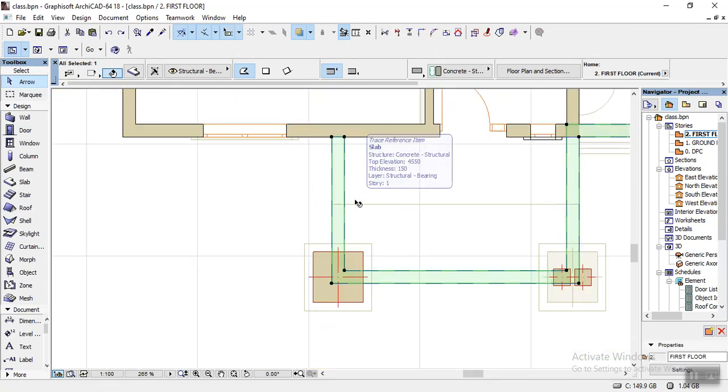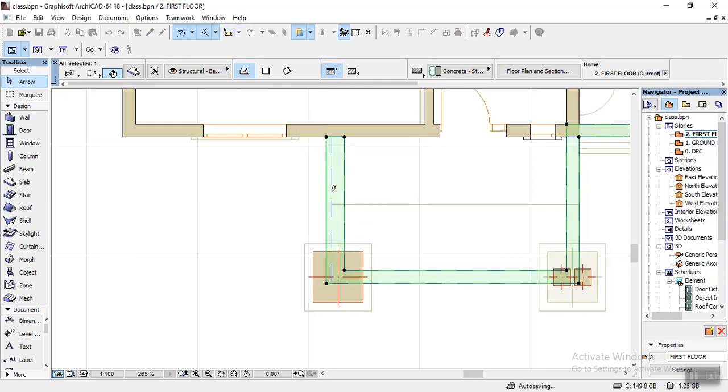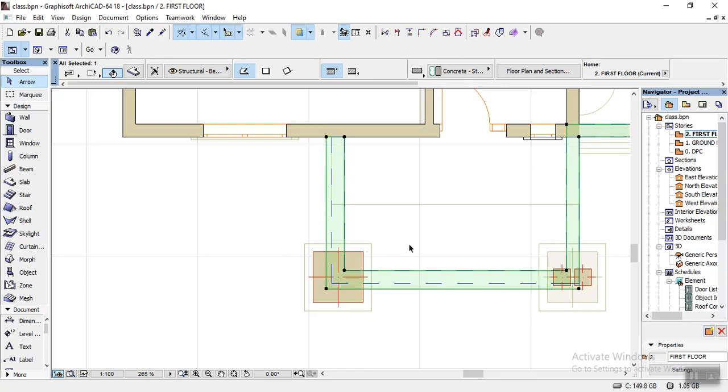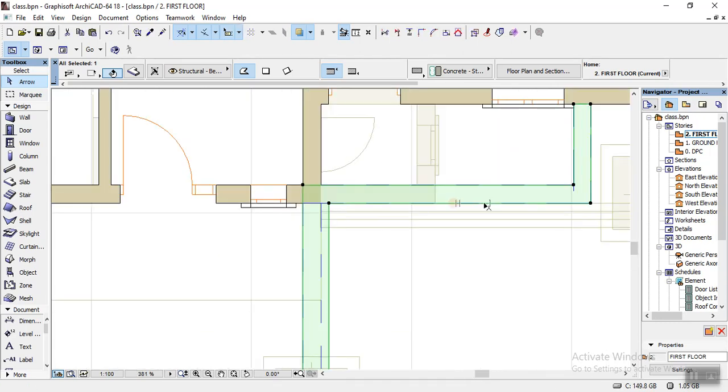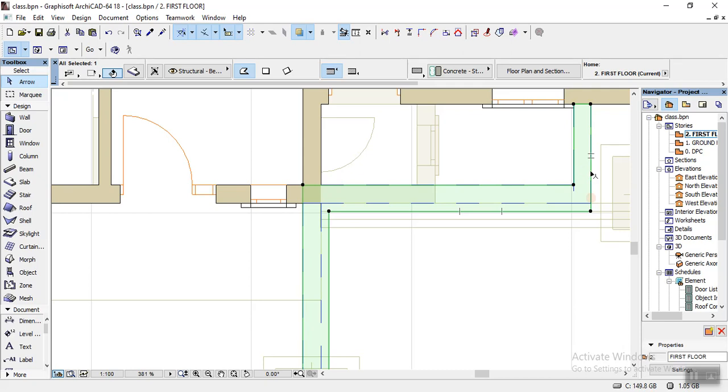Oh, sorry, my bad. I'm going to offset just this. It was offsetting all edges, in and out, but I really don't want it in and out. I just want only the outer part of it. So I'm going to offset this edge, one part, 100 millimeter. I'll come down to this spot, offset this to 100 millimeter. I'll offset this to another 100 millimeter. I'll repeat the same thing here, 100 millimeter. I'll do the same thing here, 100 millimeter.